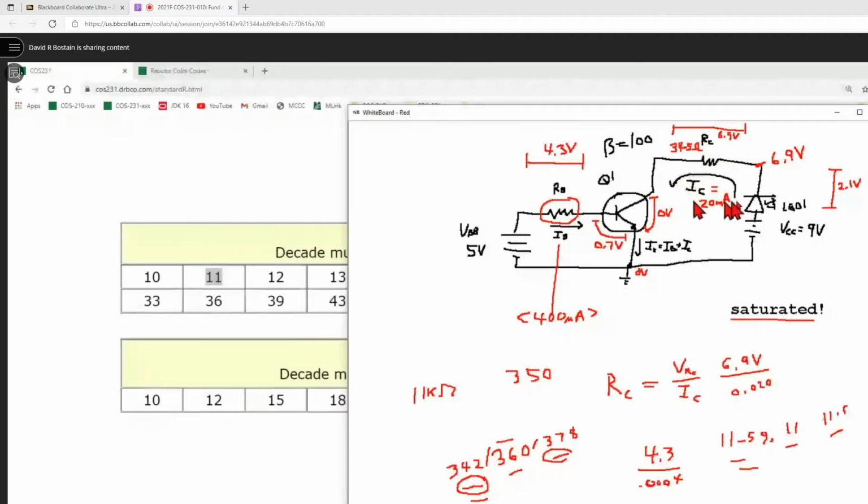If we go buy the resistors, and I give you an LED, which is really 2.1 and uses those specs, a transistor that really has a beta of 100, and we have a 5 volt, 9 volt power supply. If we built this, this would work. It's not maybe it'll work. It's not, oh, this is too complicated, we need to do more calculations. No, if you followed my procedure I just gave you and you hook this up, this transistor will work in a saturated form. If we put a switch in here, we can turn this light on and off, even though we could assume that this piece here was a pin on the microcontroller that couldn't provide 25 or 20 milliamps of current. Why that's useful? Transistors are the basis for building digital circuitry.